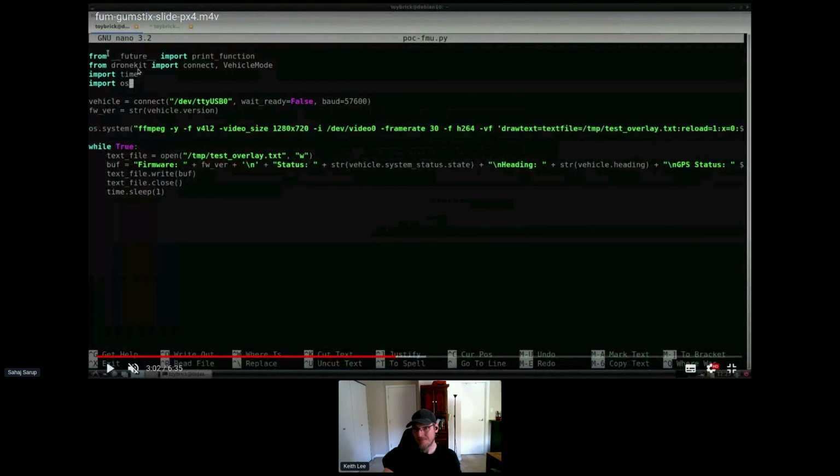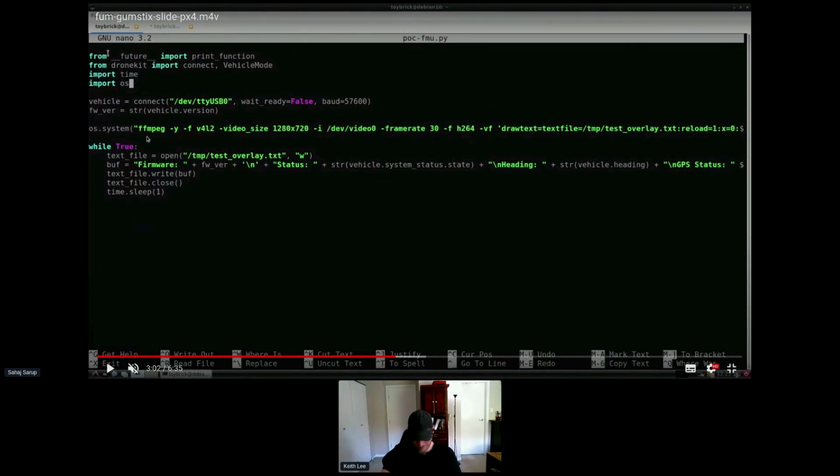If you don't want to manually deal with the Mavlink Python library, which can be a bit overwhelming because you have to do a lot of manual setting up of strings and then passing them, you can just use a library called DroneKit. It's a wrapper around Mavlink. It does all of the complex stuff for you. You create a vehicle variable and just connect to it.